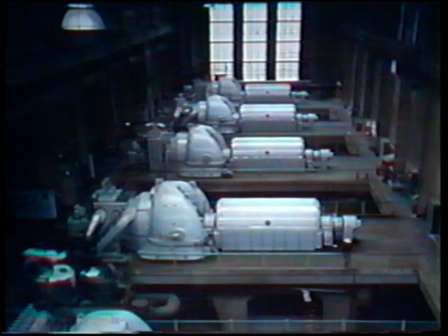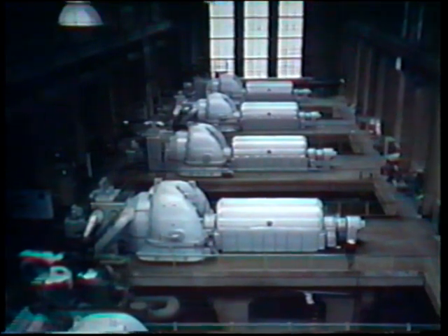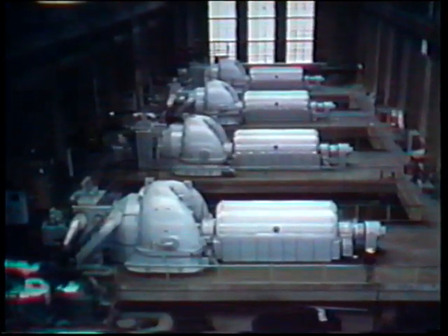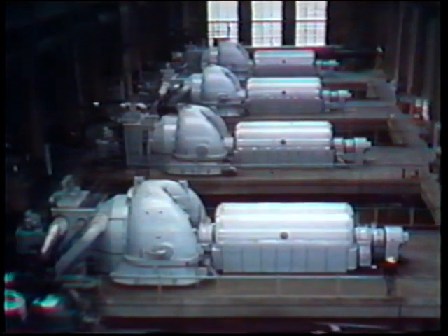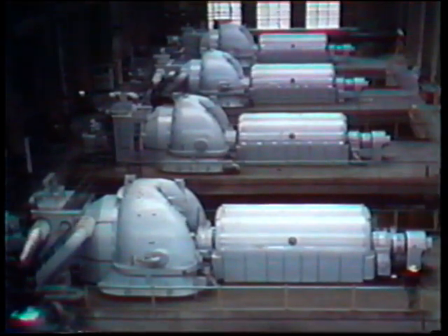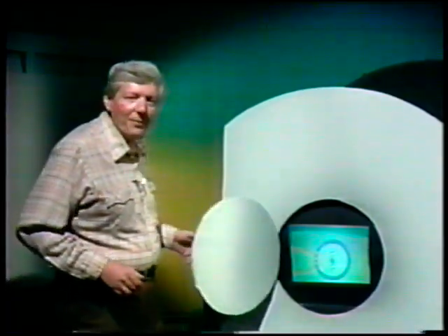As you probably know, all generators use induction to create an output voltage. When a generator is connected to a circuit, this induced voltage causes current to flow through the circuit. For voltage to be induced in a conductor, three requirements must be met. They are a magnetic field, a conductor, and relative motion between the field and the conductor. Let's look at how induction is involved in an AC generator's operation.